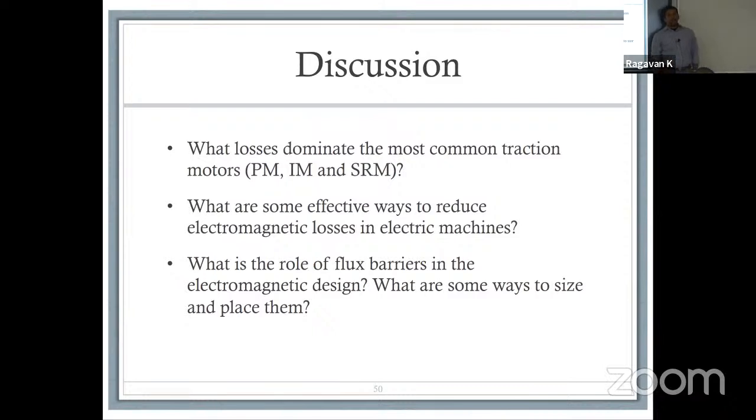Okay, so once again, this is just my thought. If you're trying to optimize the design, you definitely have the option of parameterizing, right? You can go into ANSYS and parameterize it. You can decide specifically, not for the shape itself, but you can parameterize different lengths. It will create multiple geometries for you.